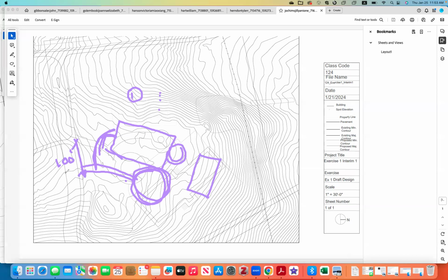The second step, I would say, is to move the entry road to 100 feet away from the intersection, meanwhile keeping it 50 feet from the vegetation. Easiest way to do it would be offsetting, or you create a separate P line for the boundary, the edge of the vegetation, and then you offset by 50 feet, and that gives you the lower edge of the entry drive for the bus drop-off.